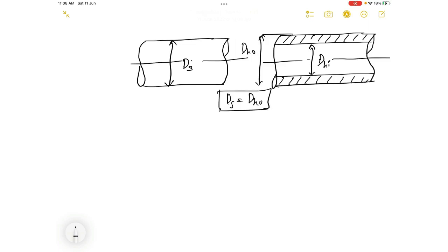This is the condition. Now as a design engineer, if you have to use one among the two shafts, which one would it be, provided it is going to be used for some spacecraft application? Okay, now in order to make this decision you have to find the torsional shear stresses for the two shafts, and based on that you can arrive at the final choice, right?